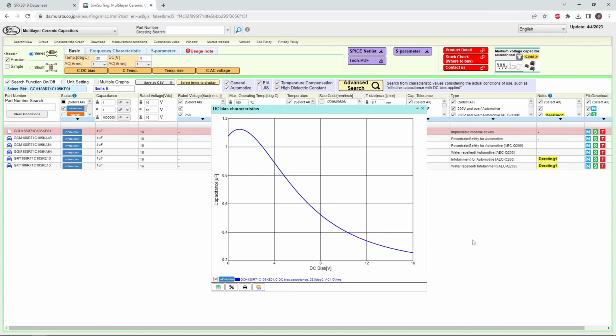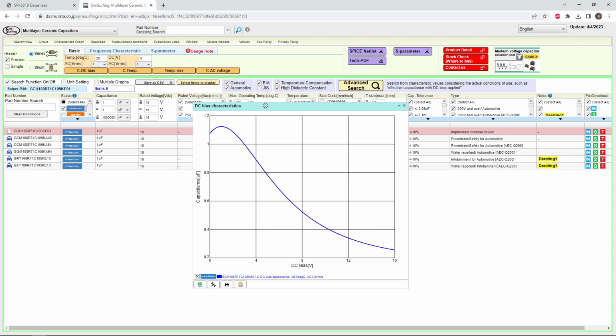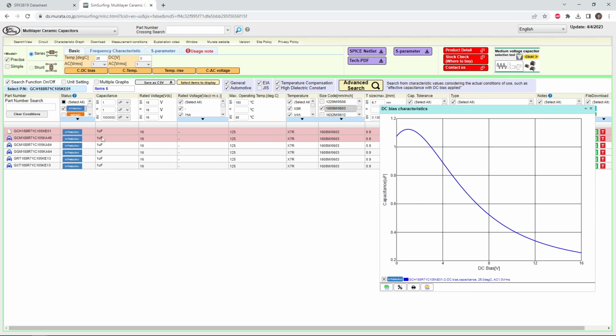On the note of choosing the right capacitor, what you also need to pay attention to, especially for ceramic capacitors, and especially for class 2 ceramic capacitors such as X5R, X7R and so on, is the DC bias derating. Typically, capacitors, for example, the one I chose here from Murata, this very lengthy name, is nominally a 1 microfarad capacitor, 16 volt maximum rating, a given temperature range, given dielectric, and a package size of 0603 imperial.